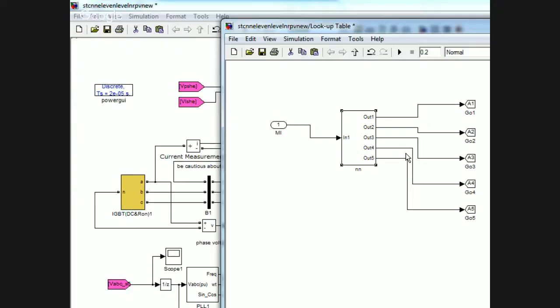DSpace can take data only from 0 to 24 volts, not more than that. So in that place, you scale it down. If it is an AC system, you can have CTs or PTs, like current transformers and potential transformers, to reduce the voltage to your limit and then you can give it. Or if you have a DC system, you can have some sensors, or even potential dividers.